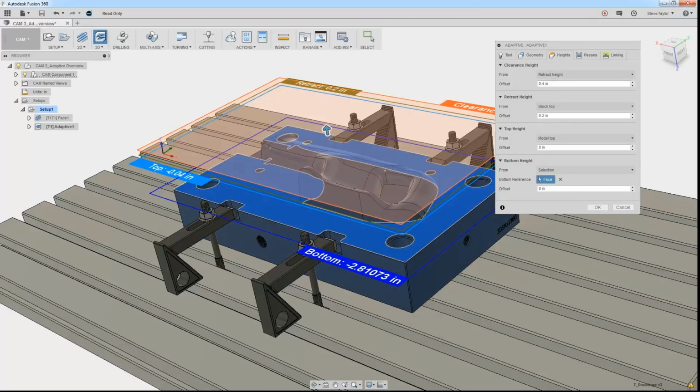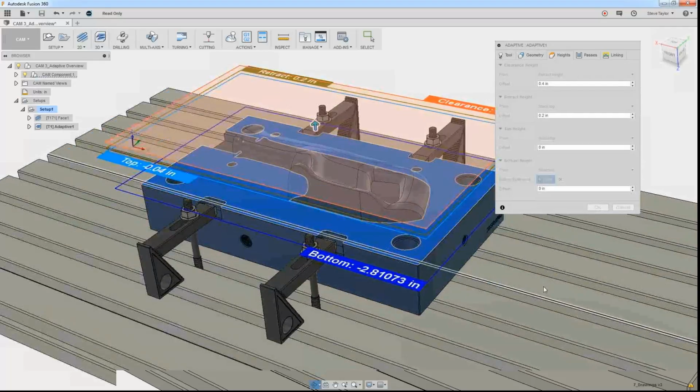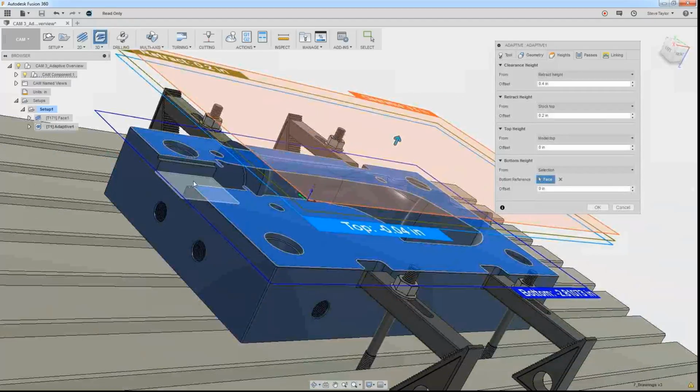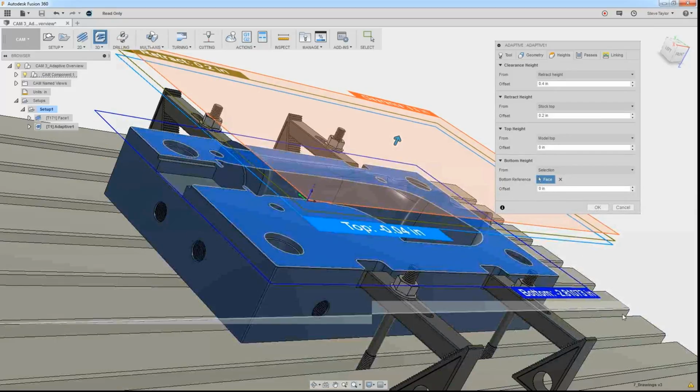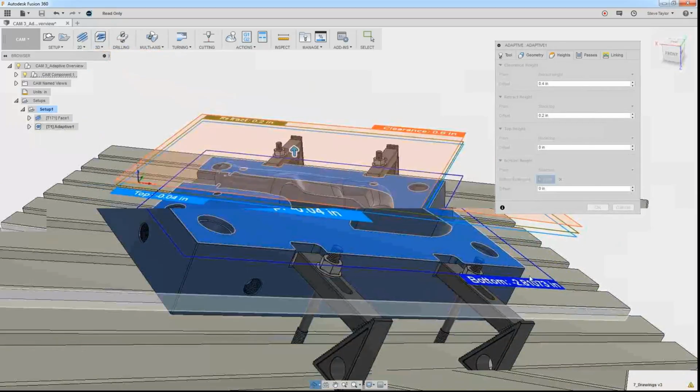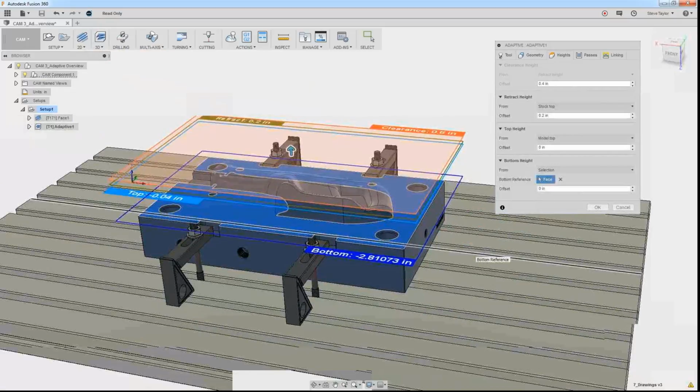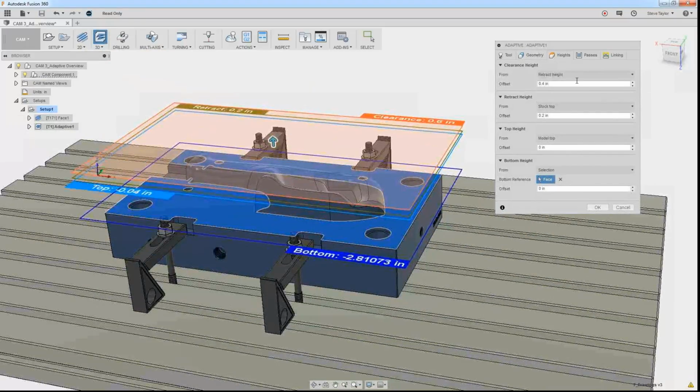At this stage, we're forgetting about this end section that goes below the face. So as we're looking at this now, I'm forgetting about this little section here, because we're going to come back and do that in a 2D roughing strategy. This is going to be our 3D adaptive one, just as we're there. We can then go to the Passes tab.